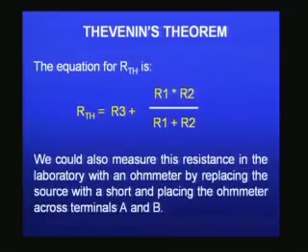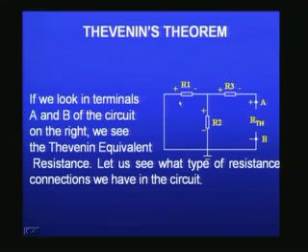Now, we can also calculate in this simple circuit which contains only 3 resistors R1, R2 and R3, what is the equivalent resistance. I am sure every one of you knows about it. You can see R Thevenin is actually R3 plus the parallel combination of R1 and R2. Let me go back and show you. You can see R1, R2 are now in parallel, because these ends are the same for the 2 resistors, these ends are also the same.